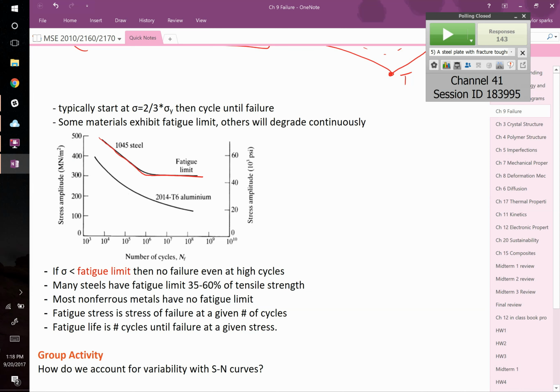Is that like a torsion or a tensile test? It's a type of bending test. It's a bending test that's alternating. It's like an alternating bending test, right? Because if you took this thing, and if I were to start bending it, the top is under tension, the bottom is under compression. And if I switched it, this is basically automating that process by spinning it, right?